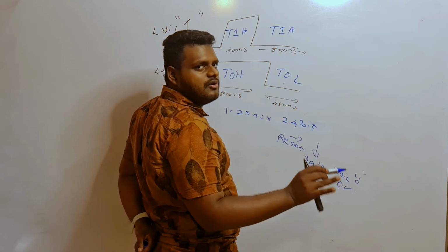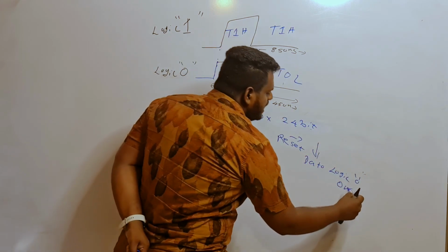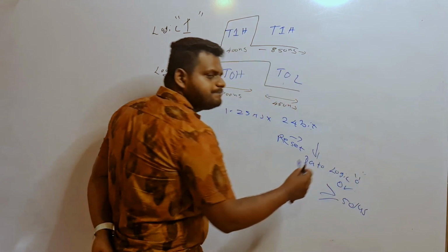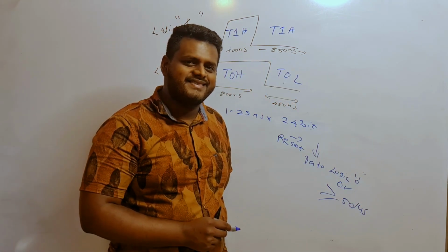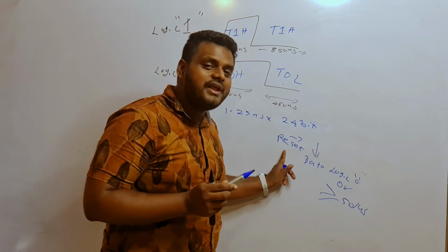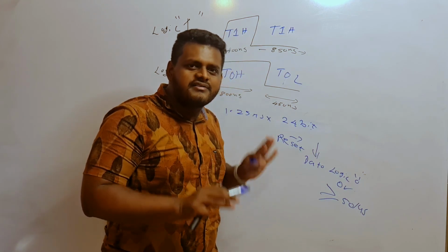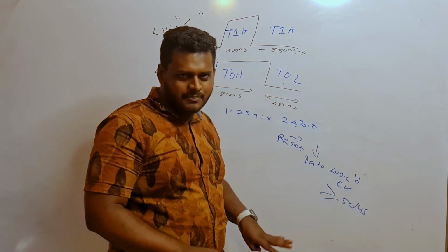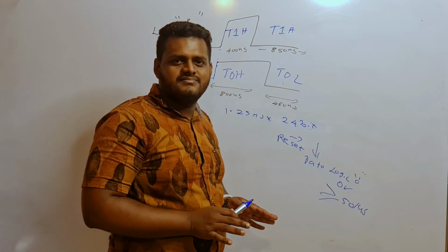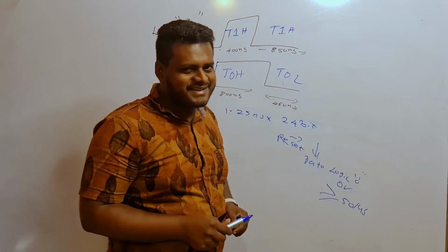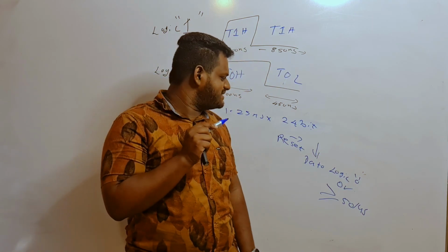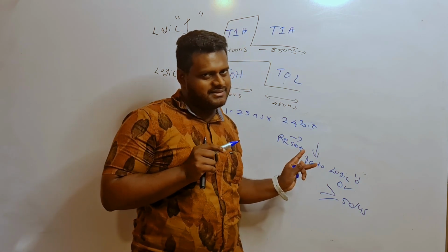That means no input on the data pin for more than or equal to 50 microseconds. Did you get the point? To reset, put the data pin low for more than 50 microseconds. That is the magic. They're using the reset method.